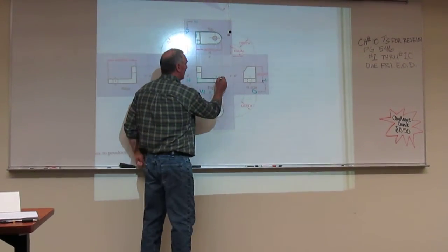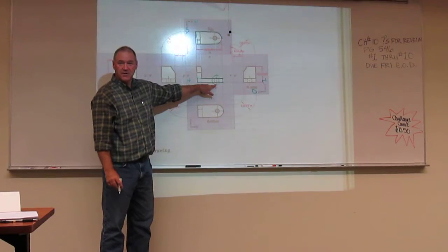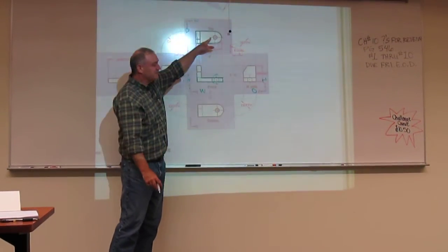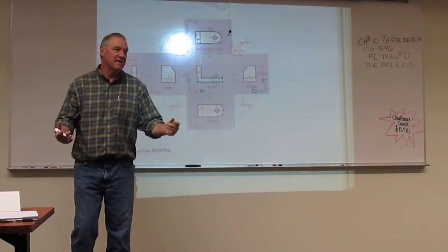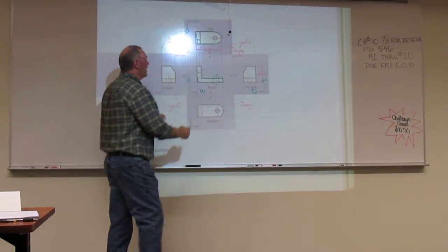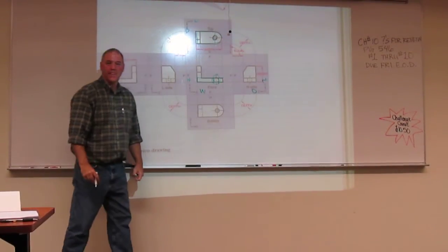Now, let's look at the hole. In this view, we have the rectangular view of the hole. We find that it goes all the way through the object. Here we have the circular view of the hole, which gives us the diameter, or radius, right? Same size as a drill bit or something, so somebody can make this. The hole is completely described here and here. Okay.